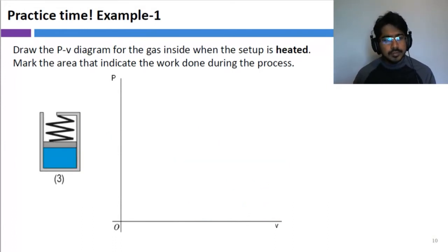Perfect. So now let's try this process. Try to draw the PV diagram for this process. Volume increases until the piston touches the top. Volume increases, definitely yes. Pressure keeps the same and then increases when the piston touches the top. That part is not accurate. Pressure and volume increase until it hits the higher spring resistance, and then only pressure increases.